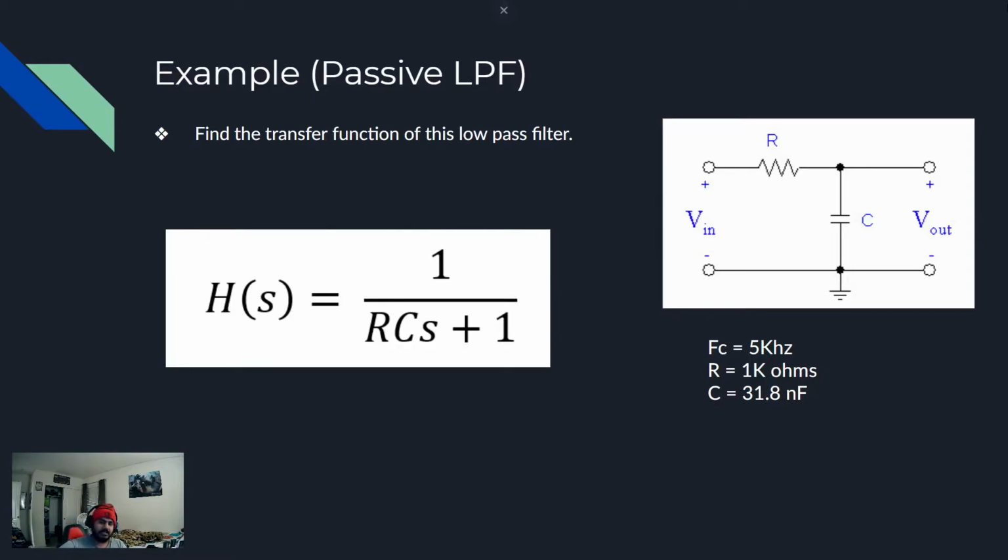So as you can see, we have an RC circuit with a V in, V out, and two components, a resistor and a capacitor. Now, when it comes to designing filters, you have to assume certain variables. In our instance, we have to assume the cutoff frequency. So I'm just arbitrarily going to set the cutoff frequency equal to 5 kilohertz. Arbitrary, you can pick whatever you want. And since we have two different components, I also have to set one of these components arbitrarily.